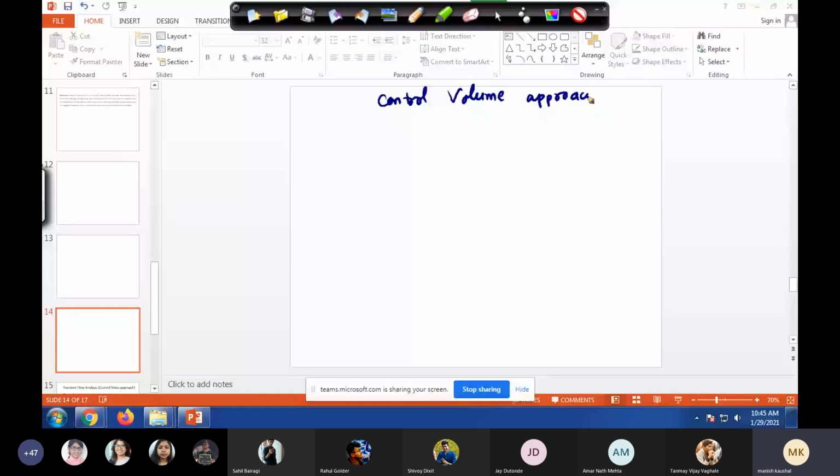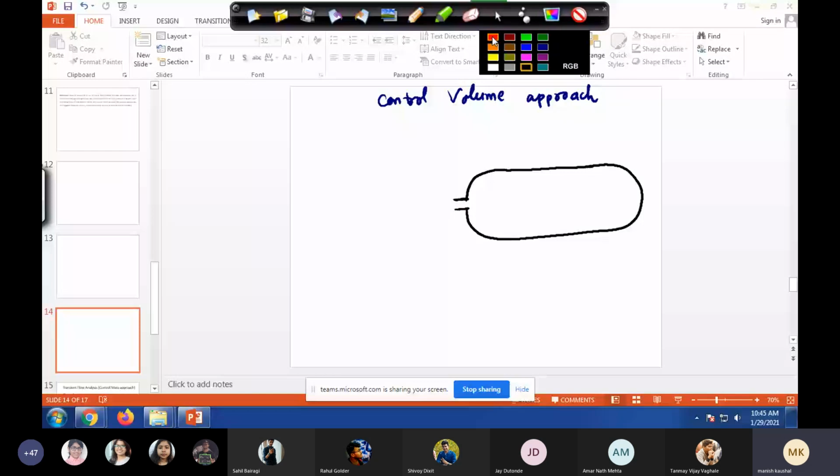So we have a tank. And this is the mount where charging is taking place. So let's draw our control volume. Of course, it is just in the vicinity of this tank wall. So this is my control volume. And it's a control volume, it's not going to change. Throughout the problem, it will remain the same. So this is my CV. Okay. Right. Now, let's apply the first law.